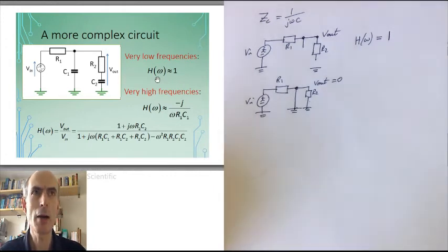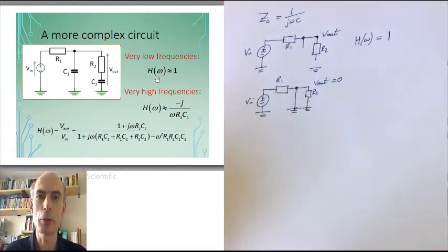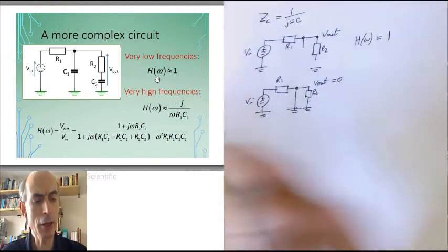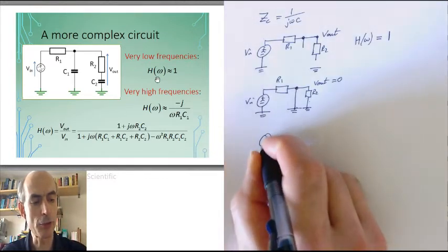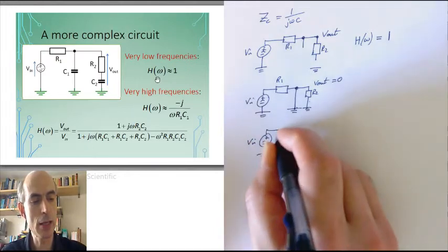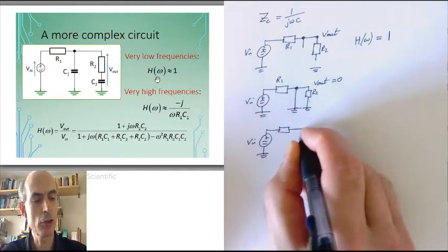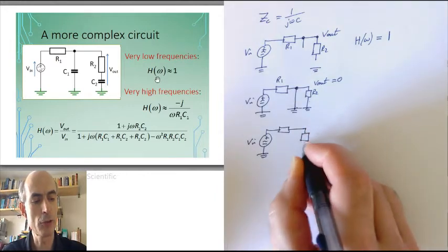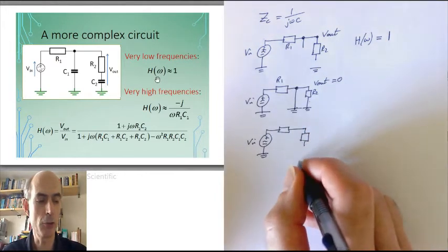So I have to do a bit more thinking to work out a reasonable high-frequency approximation. And I might proceed like this. First of all, consider that the capacitors are not 0 impedance, but just a very small impedance.